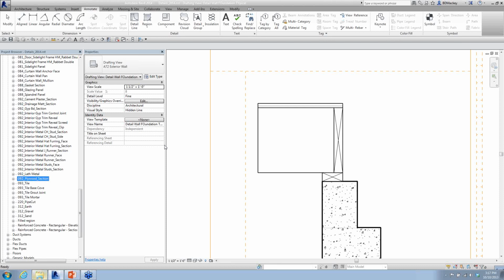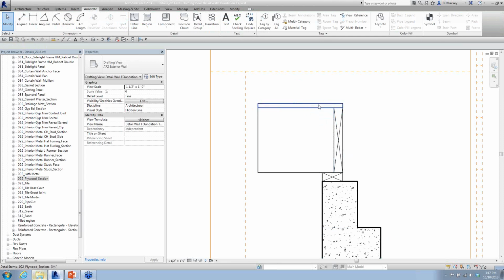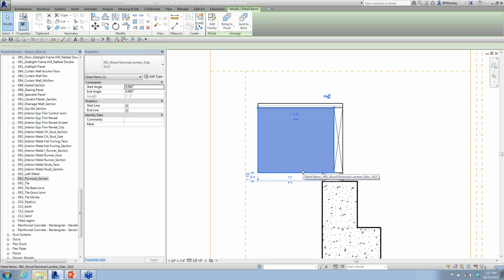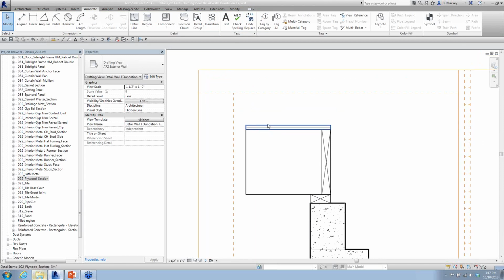And what you'll see in detailing part 2 is how to create these families, how to do those families and take them and save them out as. Because for me, I started with a gypsum wallboard family, did a save as, made it my concrete, changed the hatch pattern, did a save as, changed the hatch pattern, made it my plywood, did a save as, changed the hatch pattern or change it to a masking region, make it my side for my 2x4s, and basically I started with that one line-based family and ended up creating a good 75 to 100 families off of that one. So you get started with that one, you get it set up, and you can go through and really start getting into what you wanted that to be.